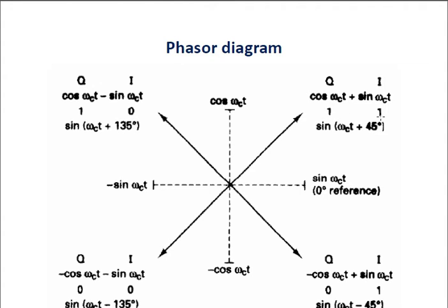Once logic 1 is transmitted, here it is 1 1 if your input is 1 1, then minus cos it is 1 0, minus minus is represented by 0 0, and minus 1 is represented by 0 1. So with reference to this diagram, we have to move in the anti-clockwise direction to show the actual data output.